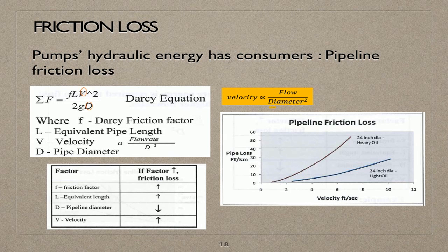In practice, there are a variety of energy losses associated with the pump flow, such as pipeline and control valve losses, which are the major friction losses in the system. This loss increases quadratically with velocity. I mean the loss for flow friction. Another loss is when there is a sudden contraction or expansion, which is also proportional to the velocity squared.